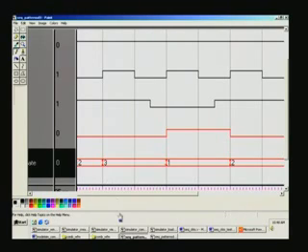It changes from state 3 to state 1 only when the input is 0, isn't it? Yes. Here it is 0. But that input arrives so far. No, input is changed here, right? So we are changing because we have the a priori knowledge that it will change from this state to this state only at the positive edge. So before this, you are free to make the transition either here or even here, right? Even here, soon after this, right? So anywhere you can make the change. So it so happened that I put it here.